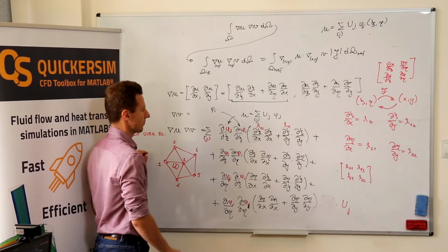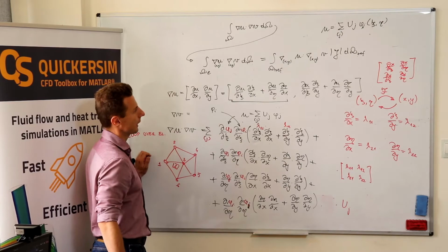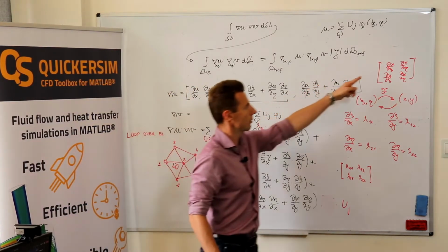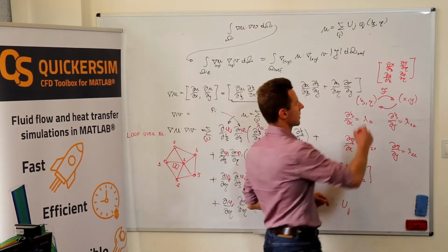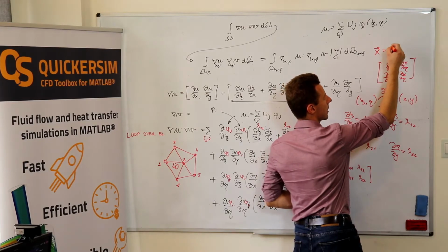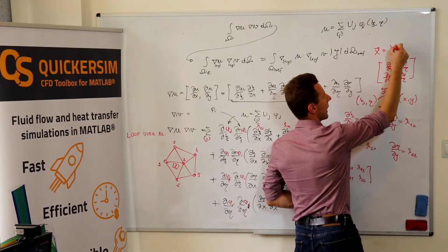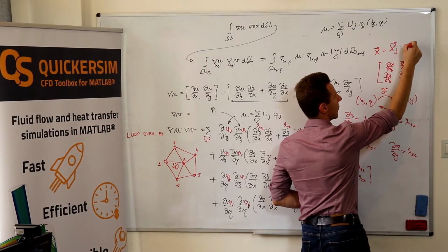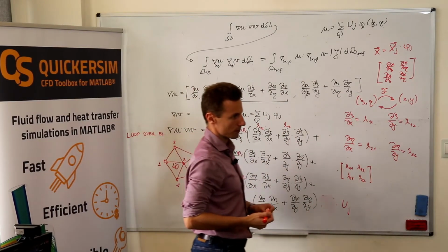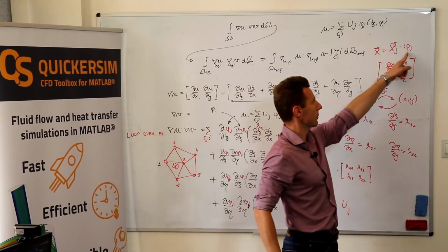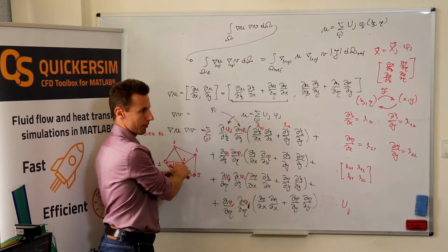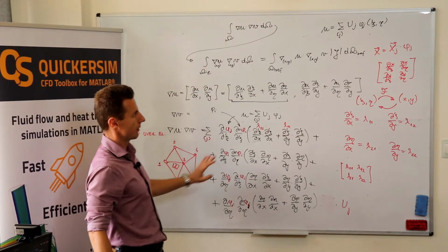You can easily calculate that because I hope you remember that you use x_j times phi_j as your geometrical transformation. So you're using the shape functions and the coordinates of the local nodes in the physical space to calculate that.